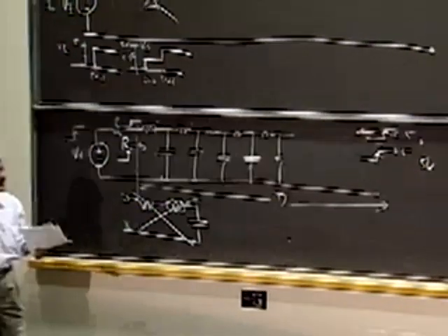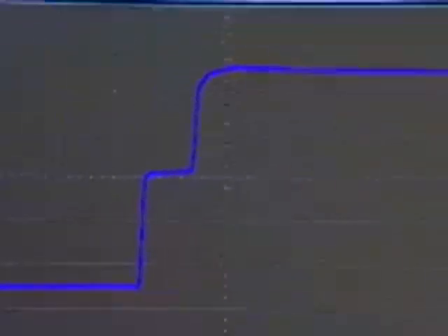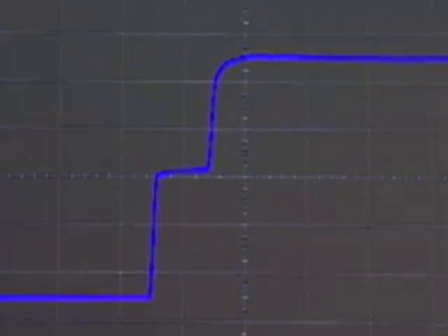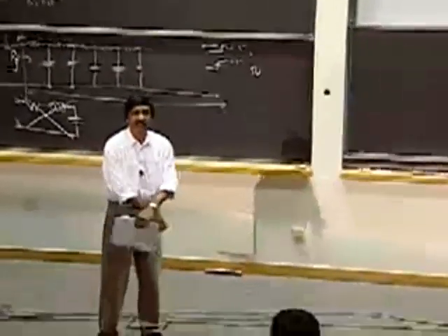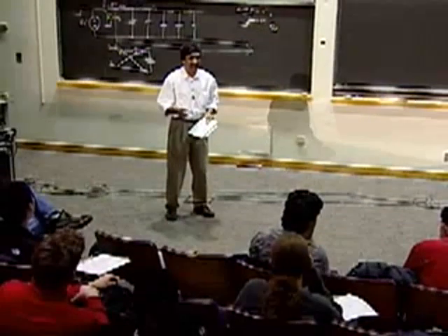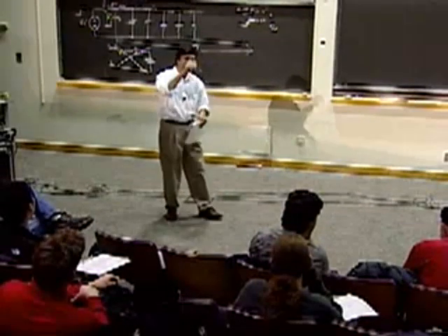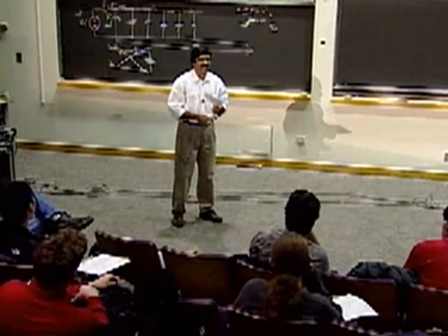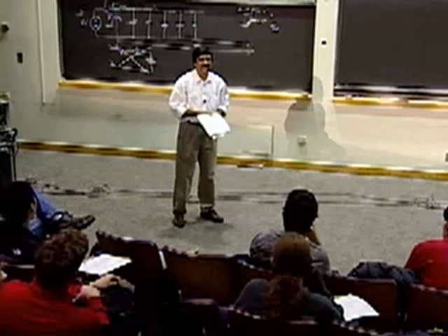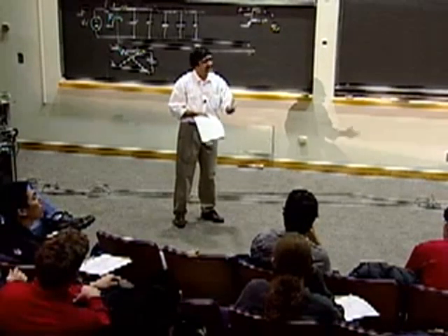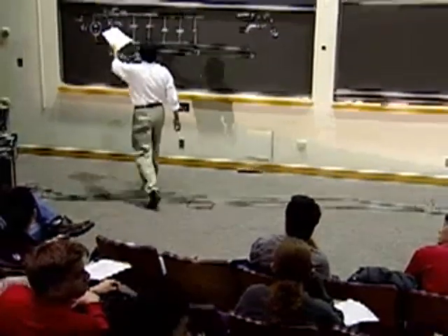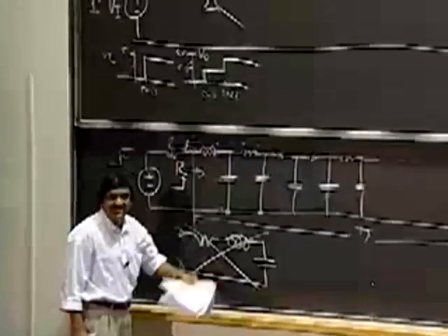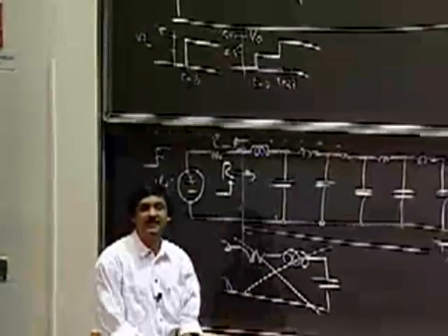Okay, so I'd like to show you a few more things here. Now, clearly, we don't want that in our circuits. Can someone tell me what problem might happen if my signals looked like this in my digital circuits? Instead of being nice little steps, if there was a little thing in the middle and then a step. What's the problem with signals like this in digital circuits? What did they violate? Exactly. This little sucker here is meandering around in the forbidden region for all of 2T. Can't do that.